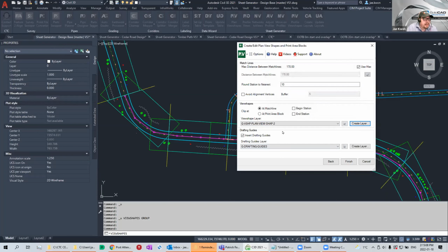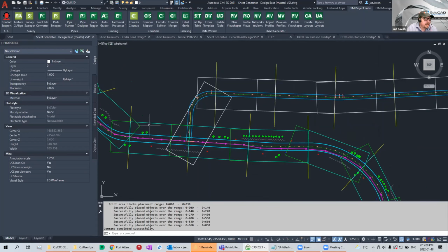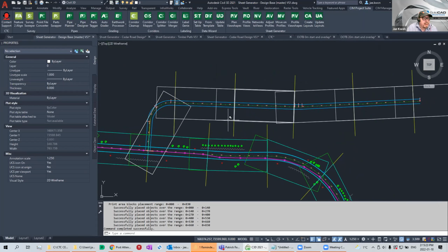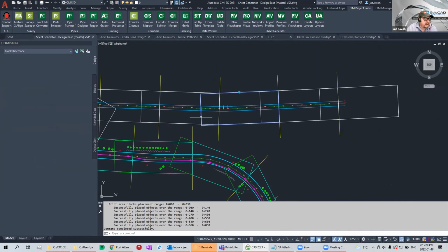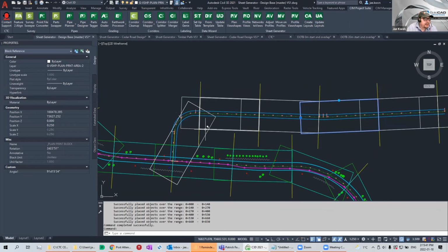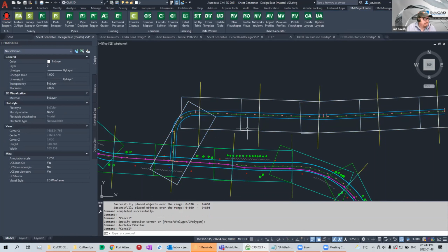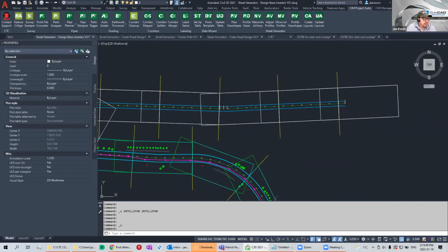So basically creating a second set of layers to generate these V shapes with, so that there's no conflict with the first set. So if I go ahead and do that, that works fine, right? The only thing is, it might be better to create the layer beforehand, because as you can see, none of the colors, line types or line weights are going to carry over from what we use initially. So if you already have those settings set, let me just undo what I did.